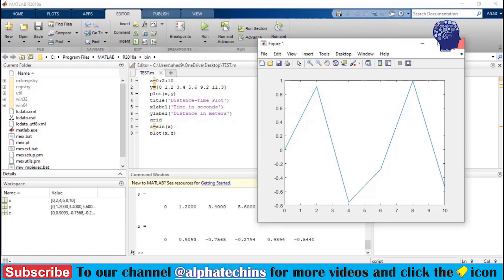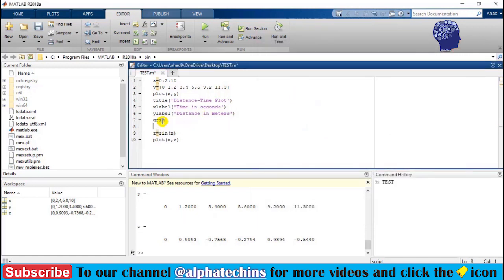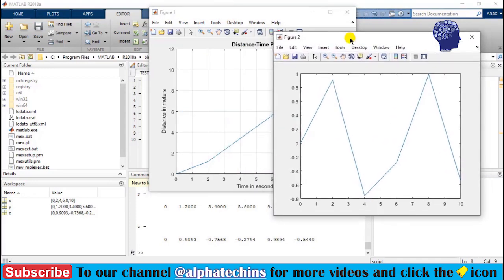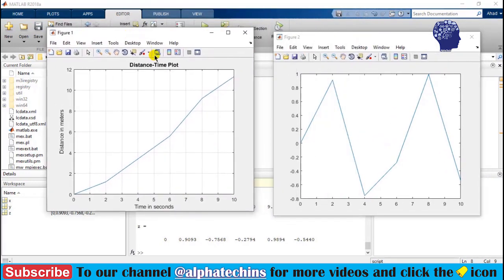So here I will type figure 2, and now I will run this again, and here you can see we have got two figures. Figure 1 is our distance time plot, and the second one is a simple sine plot. Now you also have to add another grid and X and Y label and also the title. So this is the extra work.